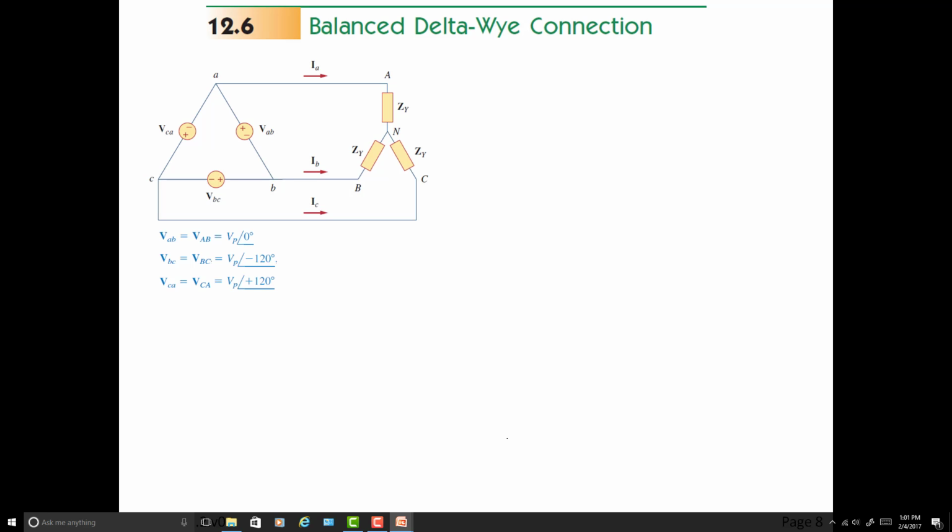It's very good. Now we're going to move on to the balanced delta Y configuration. And this is the last of the 4 configurations. So the delta Y, possibly the diciest of the 4, I don't know. But we have a couple of things we have to go after. The line voltages are already indicated. They're the same as the phase voltages. This is nice. So it's the line and phase currents that we're going to be interested in.